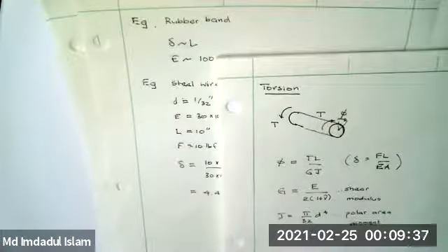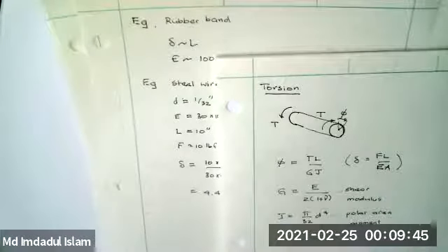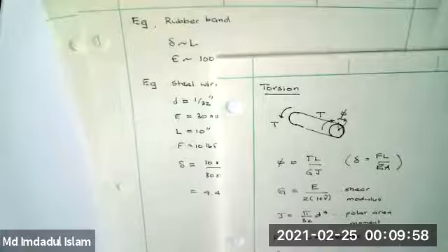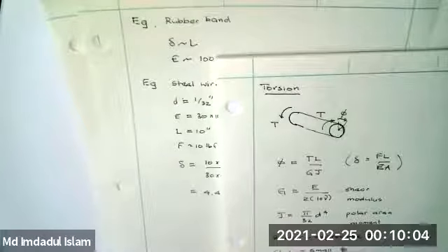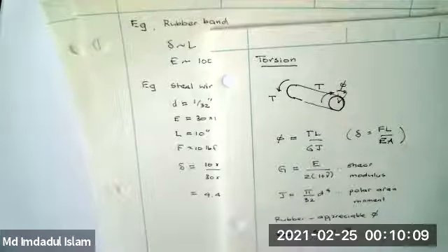Lots of books call this moment of inertia, and that's fine. That's become accepted use. There is actually no mass term in this. That's really an area moment. And again, if you have compliant material, you can get appreciable deflections. With steels or aluminums, you get relatively small.